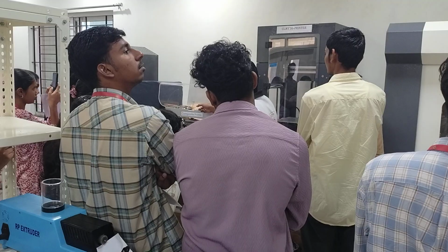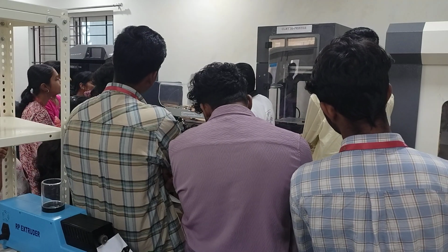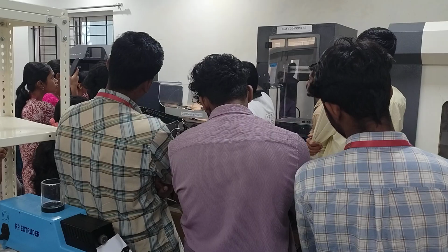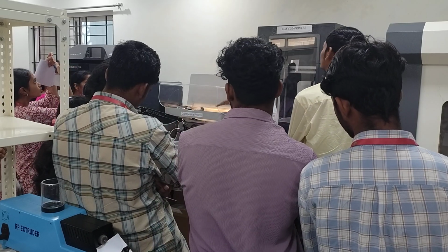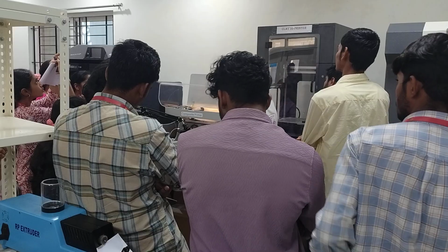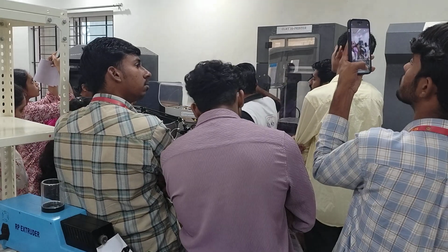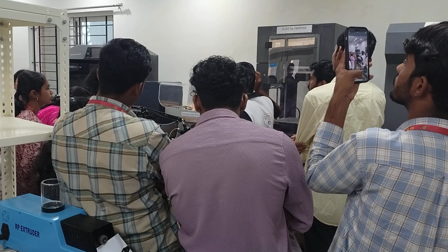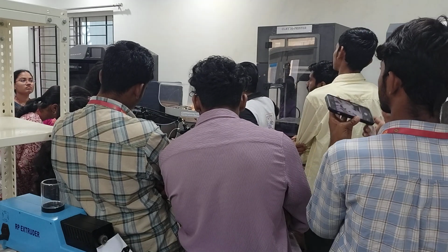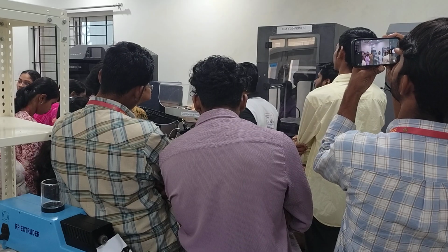So at the end, it prints something extra, which we can say is a wastage of material, but every layer it goes and calibrates. The sensor calibrates whether the printed part is at the same level as intended or not. So a kind of well will be printed at the corner and our main part will be printed here. I have made a small mistake actually, that I have not placed this glue on it. I'll see whether the print is coming good. If it is not coming good, I'll have to put this glue on it.